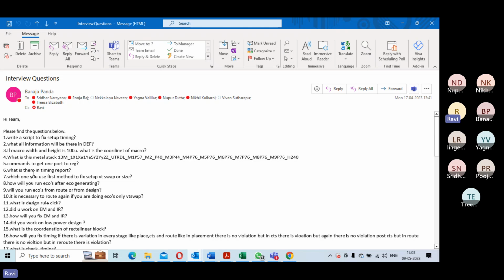And you can also mention, if you put the hyphen path type full clock expanded, then you will get the clock arrival time and also the capture clock. So that you can understand how the whole clock tree is being scaled up, etc. You can get all the insertion delay information.